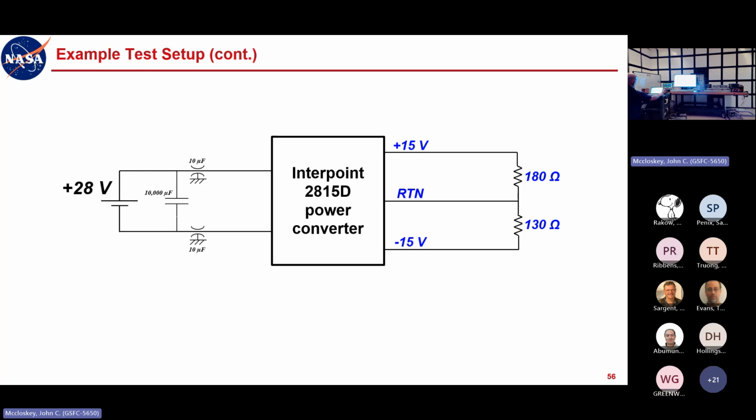What we're measuring in the line is common mode. So the measurements I was just talking about were common mode. You could think of it as mode conversion, but I think that's overcomplicating it. Just think of this as one wire. For common mode, it's just like one wire going out to some stuff here. And as far as common mode is concerned, it's basically just a wire that ends in an open circuit above the ground plane with some distributed capacitance here.